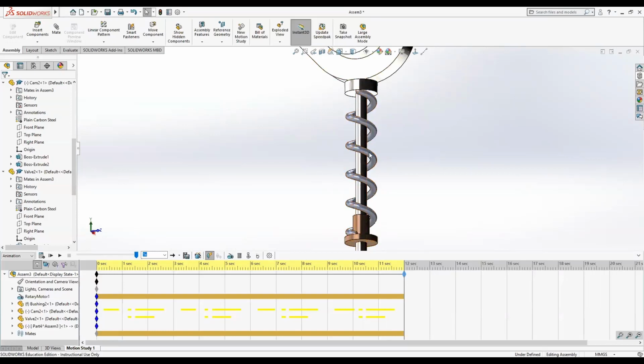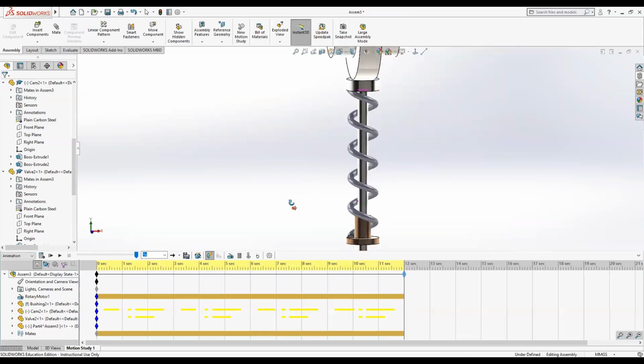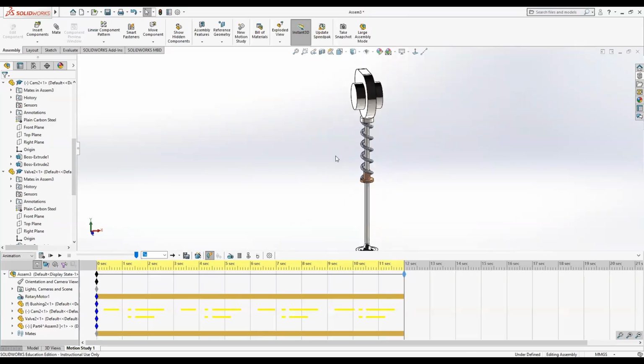And as this shaft goes up and down, it changes the length of that line. And this spring is related to the length of that line. So as that line changes, the shape of this spring changes, because remember that this spring is just a swept boss base around this line. As that line shortens, the angles of the turns change, because it still has to be 5 rotations around every time. And that's how the program draws a spring. So, okay, that's our first part.